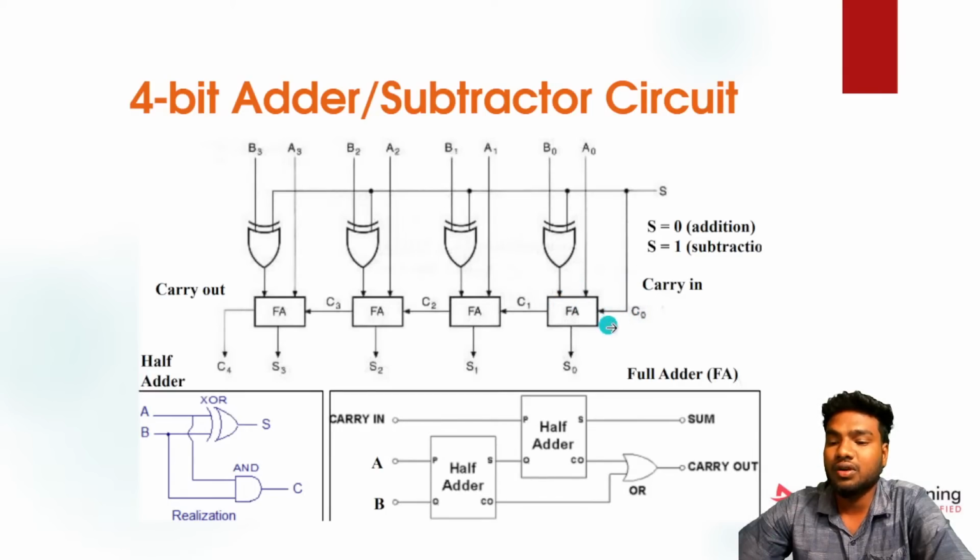we have another input for the full adder, I have given 0 for S, so it comes here. The carry in is also 0, so this is the first carry in, and it has 0, and inputs 1 1. So if I add 1 1 0, it means sum 1 carry 1. So I will get sum 0 as 1, and then carry 1. Carry 1 means I'm applying it to the next full adder from the MSB. So this is the circuit. If you pass some input through the circuit, you will get the 4-bit adder-subtractor logic.